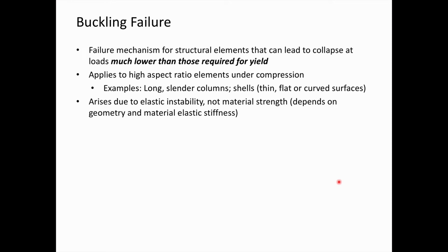This is a phenomenon that is due to elastic instability. It actually does not depend, at least in the simple case, on material strength. It depends instead on the geometry of the component, the direction of loading, and the material elastic stiffness. So keep this in mind. Buckling is connected to elastic instability.